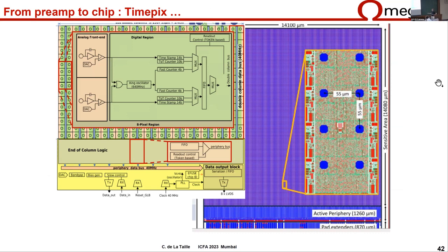which is used on, again, a semiconductor detector. So this is TimePix, designed by CERN. This was probably presented last week in the semiconductor session. So it's an array of pixels, 20 millimeters by 20 millimeters, so lots of pixels. I don't know what version of TimePix this is, but the pixels are typically 50 by 50 micron square. And so lots of little squares like that. They are grouped by arrays of 8 things.